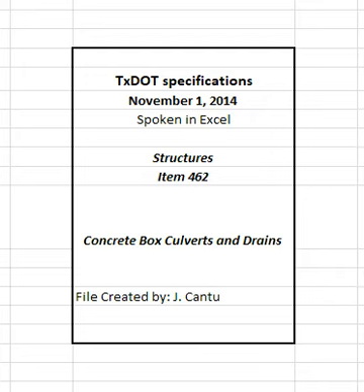2.8 Storage and shipment. Store precast sections on a level surface. Do not place any load on the sections until design strength is reached and curing is complete. Shipment of sections is permissible when the design strength and curing requirements have been met.